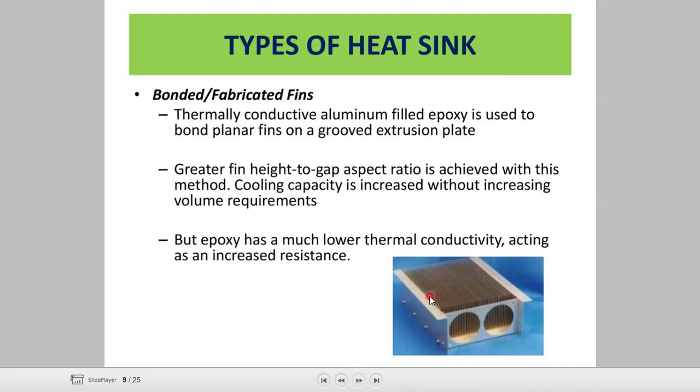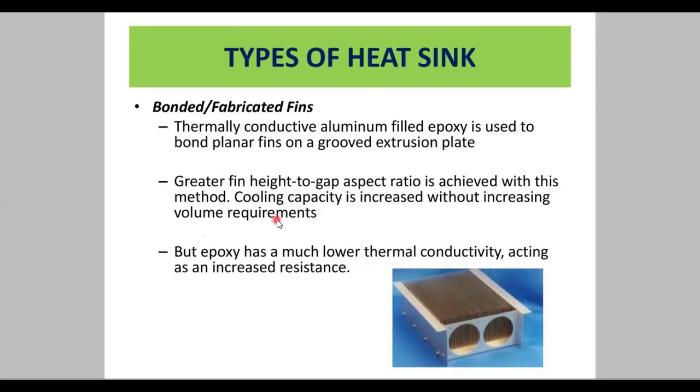Bonded fabrication fins and how they will look. Thermal conductive aluminum-filled epoxy is used to bond planar fins on a grooved extension plate. So a greater fin height to gap aspect ratio is achieved with this method. Cooling capacity is increased without increasing volume requirements.